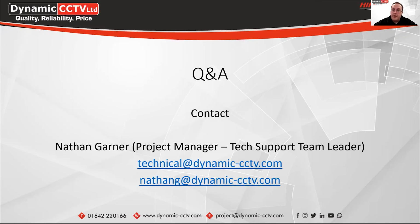Mike has asked, does TVI and IP AccuSense have the same accuracy for false alarm filtering? So they are now both on the newer Gen 2 AccuSense algorithms. The limitation with TVI is obviously that you can only have 4 channels of AccuSense technology on a DVR, whereas an NVR is dependent on you using AccuSense cameras. So if you had a 16-channel NVR, and you had 16 AccuSense IP cameras, all those could be set up with AccuSense analytics on the actual system.